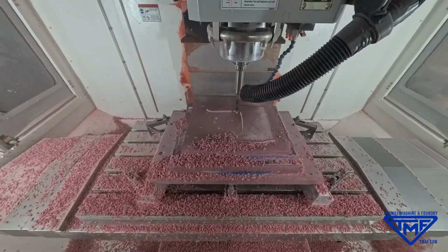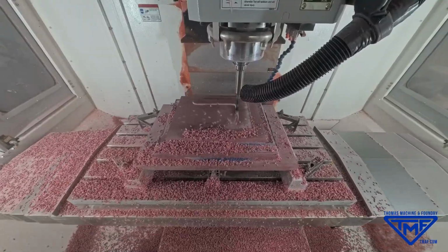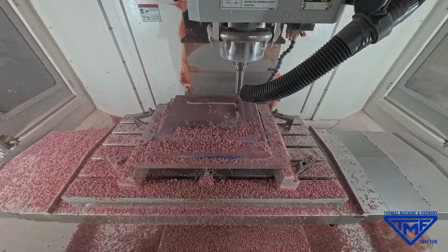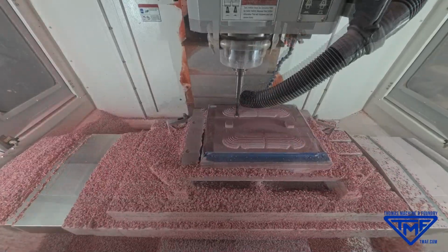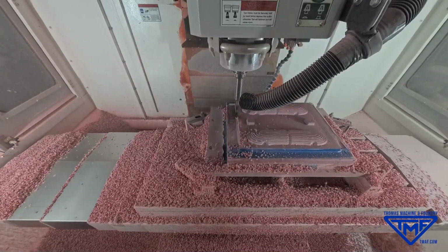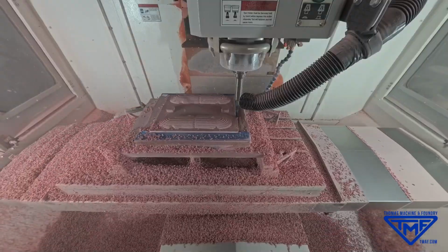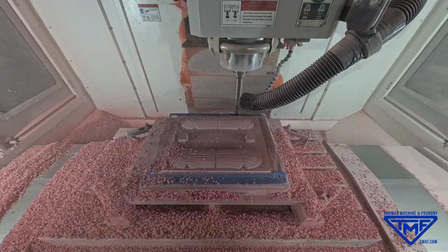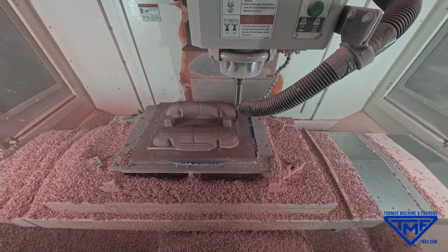Unlike cutting metal, this process requires no cutting fluid or coolant. The urethane material cuts cleanly and freely, allowing the machine to remove material without the need for traditional cooling methods. Instead, we use compressed air directed at the cutting area. This air clears chips away from the tool and helps manage heat created during the cutting process. This keeps the cutting tools working efficiently while keeping the process clean and controlled.